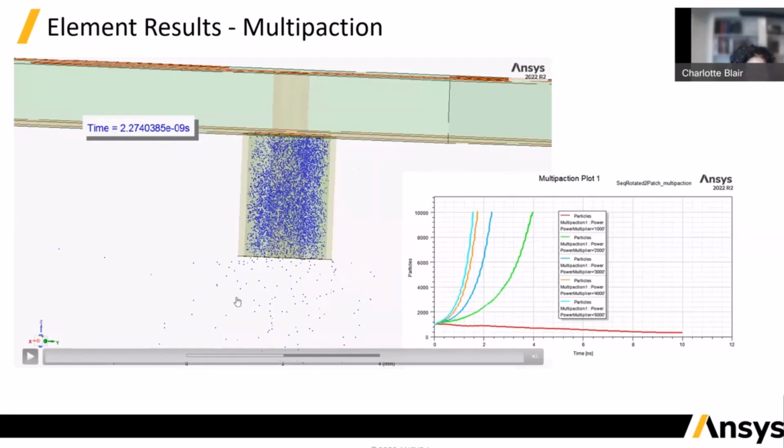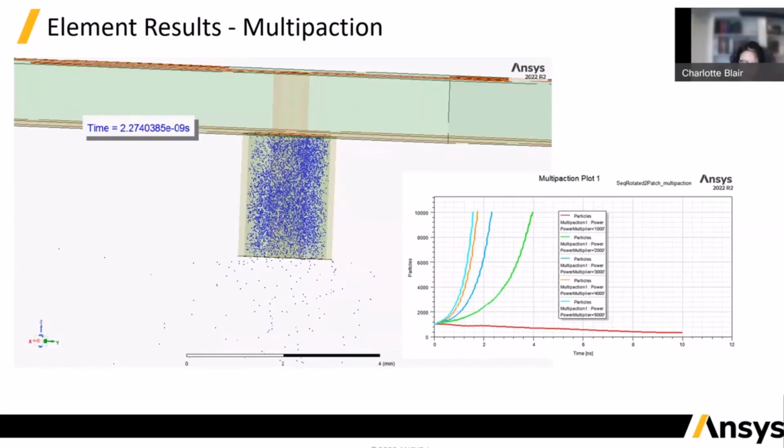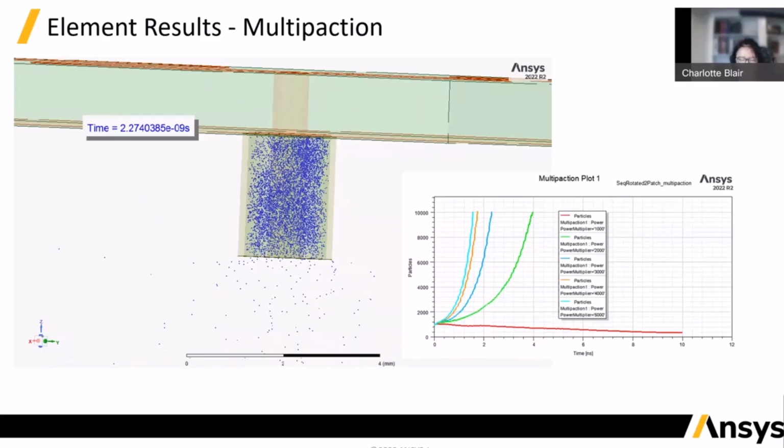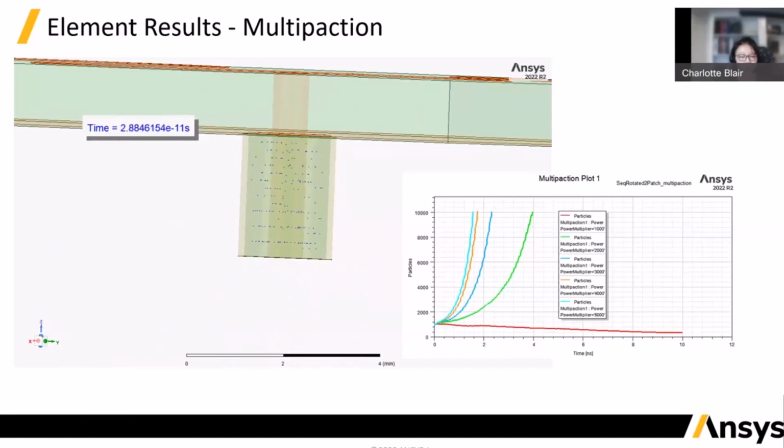You may or may not see that I had selected in the setup for multipaction the entire vacuum space. Vacuum space was not only on the inside of the connector, but in the regions inside the cavity that's enclosed within the entire antenna element. So there are electrons that are in the space outside of the connector. Again, you will be able to see that in your simulation.